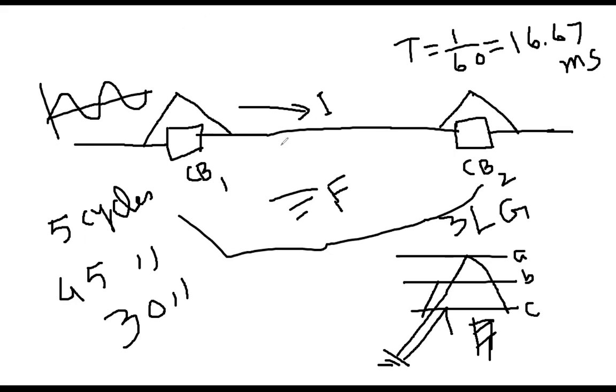But what I am asking is, I reclose the breaker because it is an auto program. After 30 or 45 cycles, it reclosed, but still the fault is going on. So what is your guess? What will happen next? So Manoj, what will happen next? I reclose the breaker after the prescribed time because it is an auto program, but still the fault is going on. The tree has touched, it twisted, and the MLGW engineer is not coming. It has been several minutes or even 1 hour, nobody is coming. So then what will happen? Then again, the circuit breaker will close and reclose again and again. Exactly. This means because it is pre-programmed, once it is closed, the protective relay again understood there is a fault.